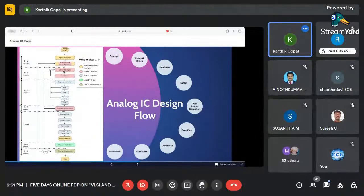Okay, so all this process will be followed. If the post layout fails, then again the engineer starts from the schematic design. What is wrong, and again you need to change. Again you need to run the simulation, and the layout engineer again changes the layout, and he runs all the rules, and then we give the post layout extraction. So this is the complete cycle. Again, it has to be done if it does not follow.